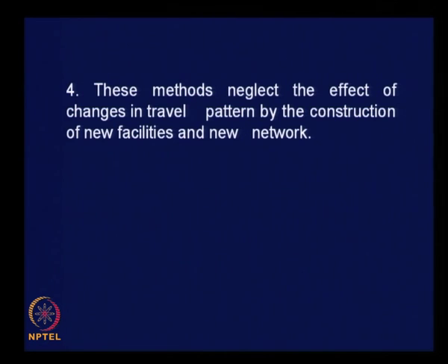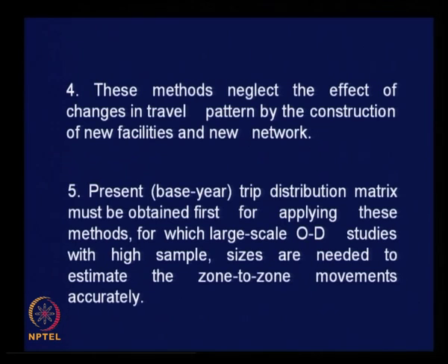These methods neglect the effect of changes in travel pattern by the construction of new facilities and new network. Right? Travel pattern itself might change. So this kind of changes cannot be accounted for in the growth factor method. Please note that all these disadvantages are taken care of in the synthetic model, namely the gravity model. We consider all these possibilities.